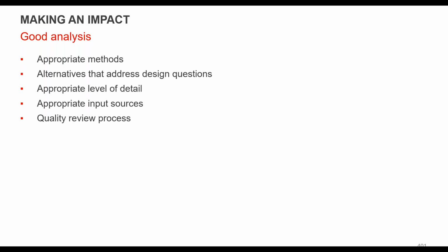In terms of having good analysis, and we say accurate analysis that is appropriate for the question that you're trying to answer, right? So make sure you're using the right tool. Make sure you have a tool that will model the things that you're trying to simulate. So we talked about that before. If you're going to be looking at radiant systems, make sure you have a tool that can model radiant systems accurately.